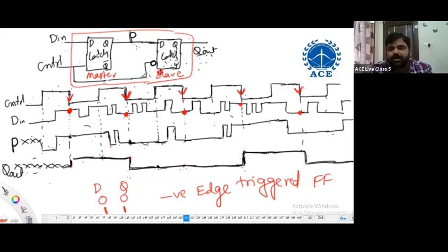Are there any rules for control? No. When there are no rules for the control signal, then how can you say that latch with clock is a flip-flop? How is clock different from control? Control can be a clock. How can it be different? If the control signal has been changed to clock, how is the behavior of the latch changing? No, it cannot change. Latch is always level triggered.